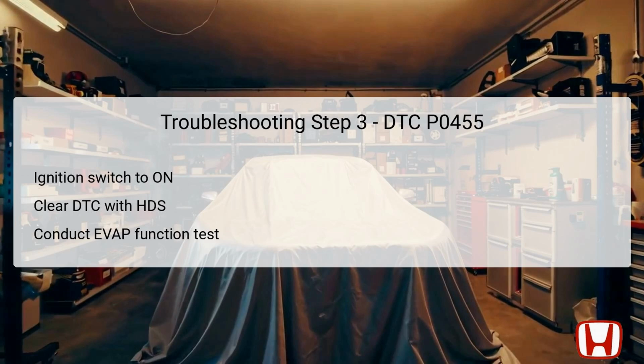Following this, conduct the EVAP function test also through the HDS. It helps ascertain if the system is now functioning as expected. If the test results indicate that the system is functioning correctly, this may suggest an intermittent failure. If problems persist, the case needs further examination.